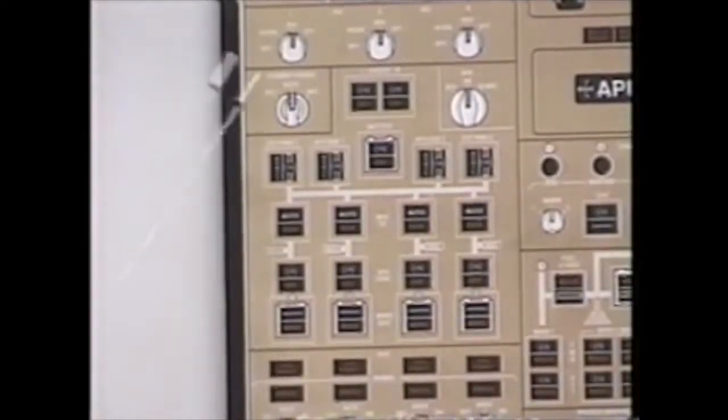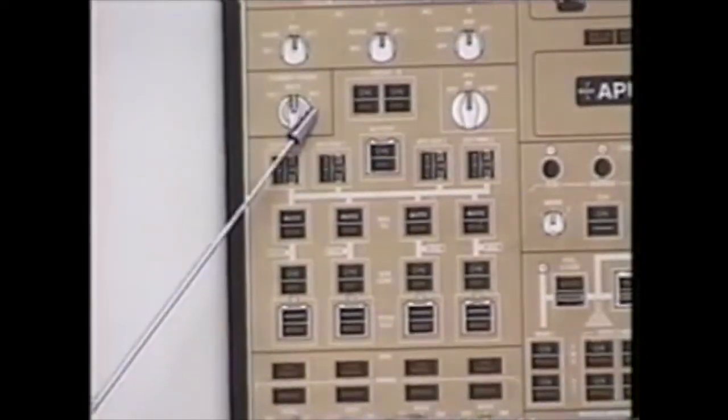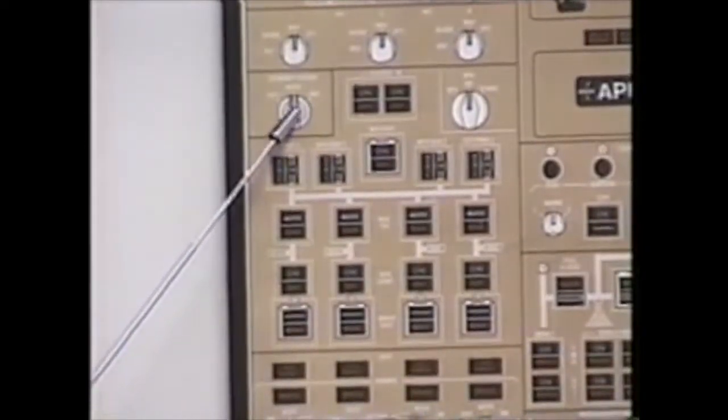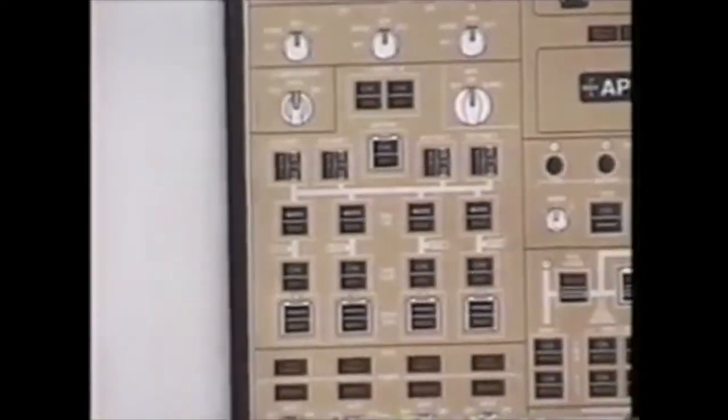During the cockpit setup, the captain is required to pre-flight the standby power system. By moving the standby power selector from auto to battery, this will force both standby buses to their hot battery buses, turning off both battery chargers. To ensure that the system works, the captain will check the